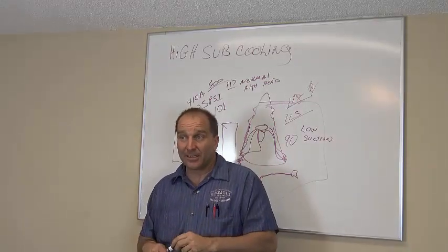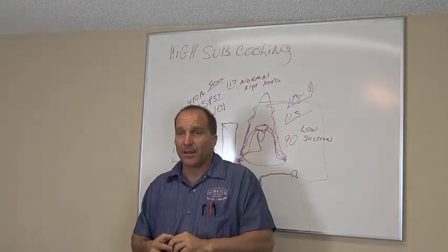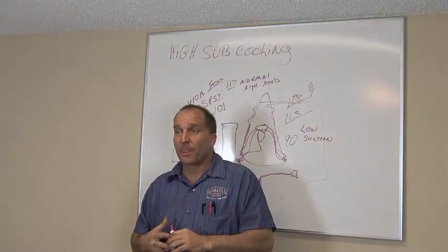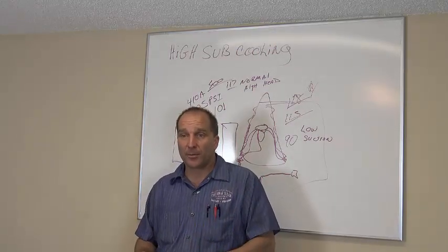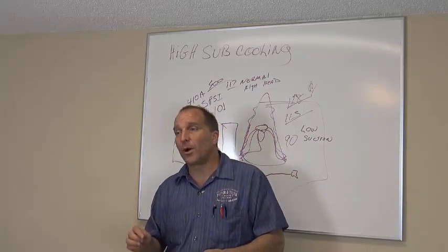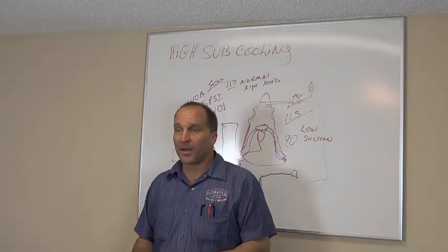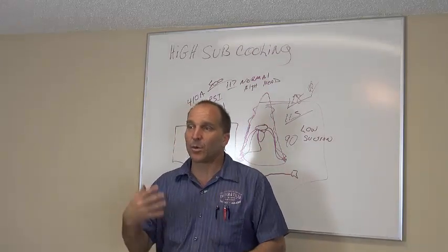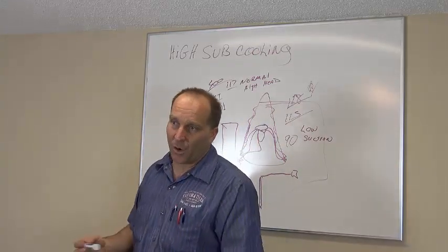You need to clean the condenser coil. Every condenser you go to, if you don't tell that customer that we need to clean your condenser properly before I can get your head pressure, suction pressure, superheat, and subcooling, you are not doing the proper job for that customer. Okay? Yes, we make money out of it, but that's what pulls the heat out of the customer's house. Let me give you a sales pitch on that, okay?